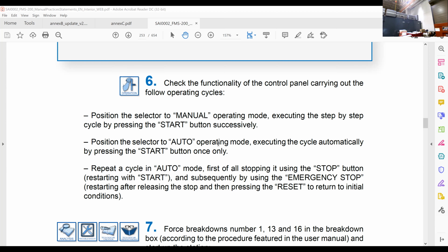Okay? So this is what takes you in the ballpark. If you flip over, at the same time that it left step 0 and initiated all those sections, it also enabled step 80 on the back page for the insertion process, which is right here. The part that gets it and inserts it into the block. So this device here is your insertion manipulator, and that's step 80 on the back. If you've got problems with this thing, you flip over to 80 and following, and your problem is more than likely visible in those steps somewhere in the PLC program. That sort of gives you, in a nutshell, how to make something so complicated look simple. Because it actually is simple when you look at one little section of it at a time.